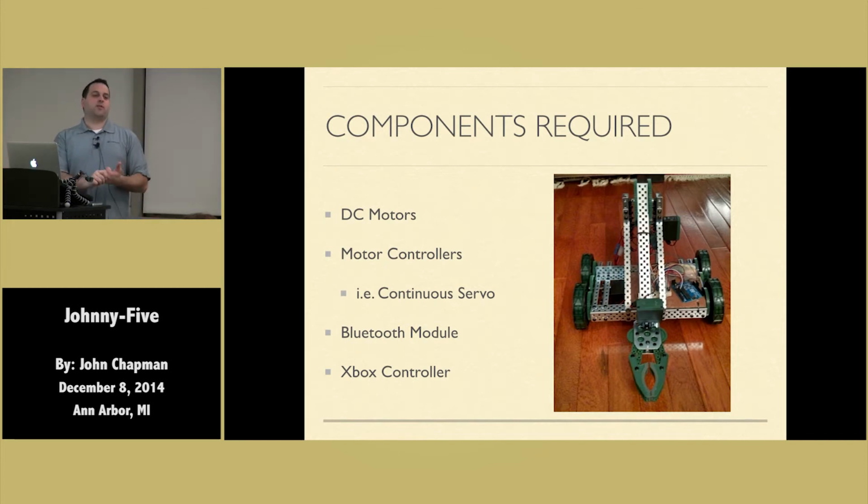We're going to use the Bluetooth module this time, so as long as it didn't break since this morning, we're going to get to see the Bluetooth module. The important thing to keep in mind with the Bluetooth module is Bluetooth has a latency of about 500 milliseconds. Because I'm driving it with an Xbox controller and the table is really small, it might fall off the front or the back of the table. It's not necessarily just because of my driving, it's also the latency involved, all right? And then we're going to use the Xbox controller. The Xbox controller is just a node module to control using the Xbox controller.